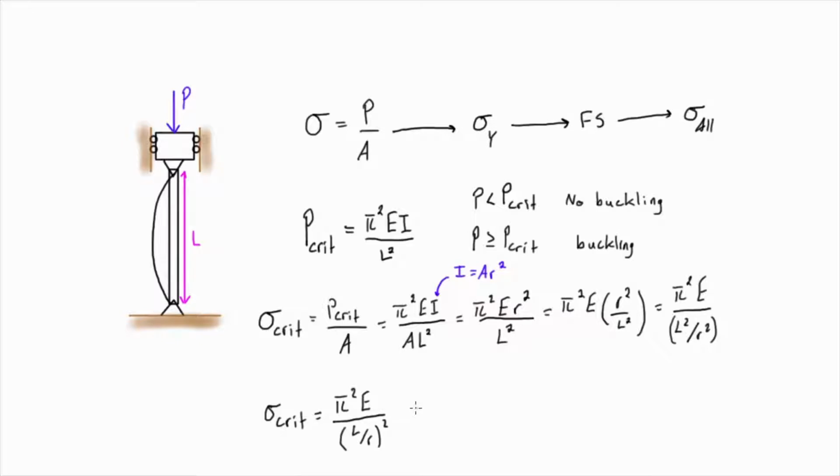Now, if the column is not circular or square, like a rectangle or an I-beam, it's going to have one short axis, and that is the direction the column is going to buckle in under an eccentric compressive load like this. So in those cases, you'll have more than one radius of gyration, and we want to select the smallest one for that given cross section.